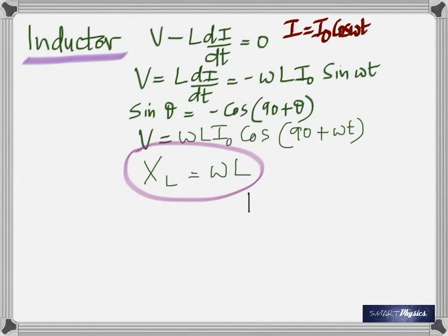Two important things, again I'm repeating. First of all, the voltage across an inductance leads the current by 90 degrees. Second one, the voltage depends on something called inductive reactance, which again depends on the frequency. Higher the frequency, bigger the inductive reactance.